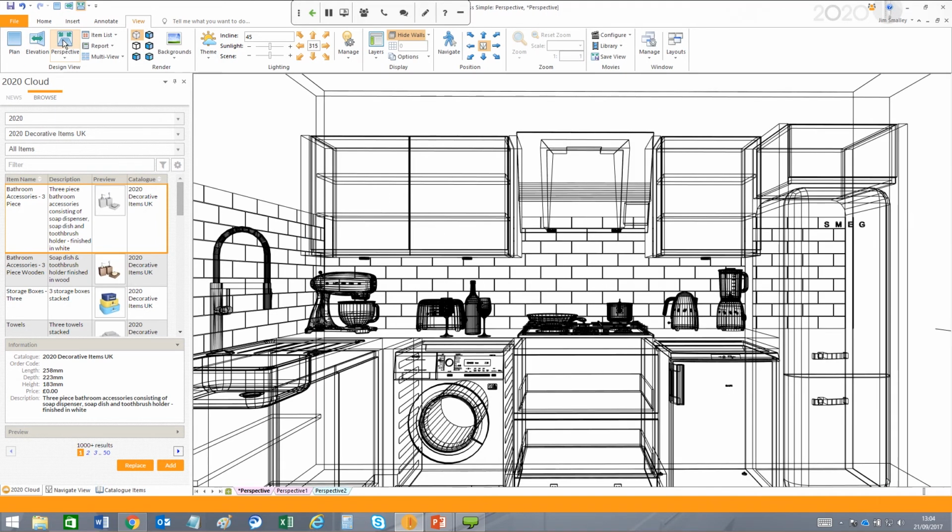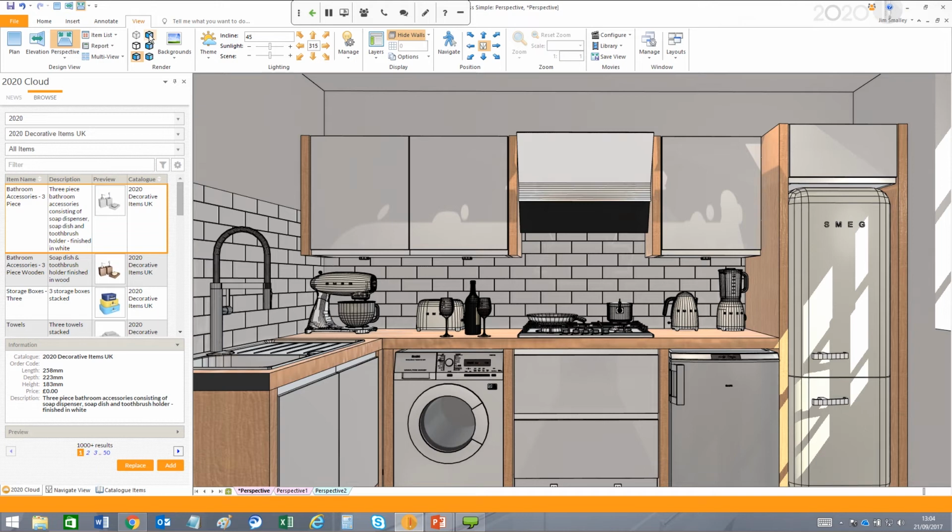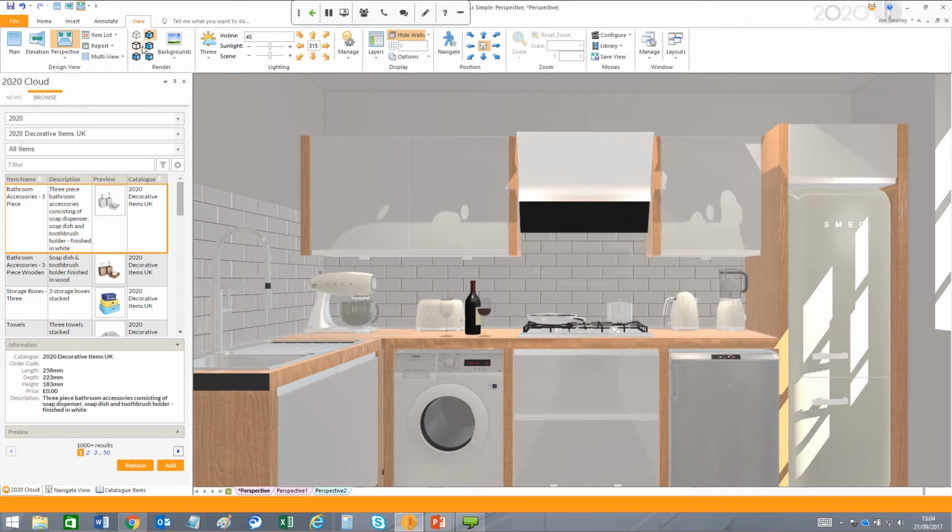When we move to perspective view, we have those same 4 renders: the wireframe, the white fill, the color fill, and the draft render. But we also have what we define as our presentation renders. We have one presentation render which still should give you a good, accurate representation of a design in very, very little time indeed. So here I am rendering a